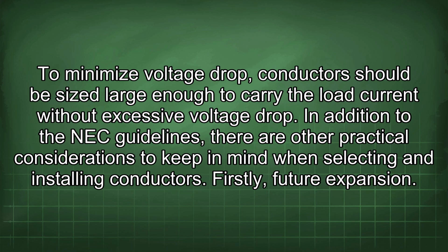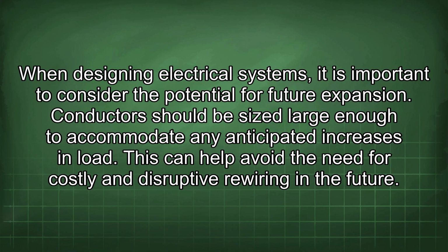In addition to the NEC guidelines, there are other practical considerations to keep in mind when selecting and installing conductors. Firstly, future expansion. When designing electrical systems, it is important to consider the potential for future expansion. Conductors should be sized large enough to accommodate any anticipated increases in load. This can help avoid the need for costly and disruptive rewiring in the future.